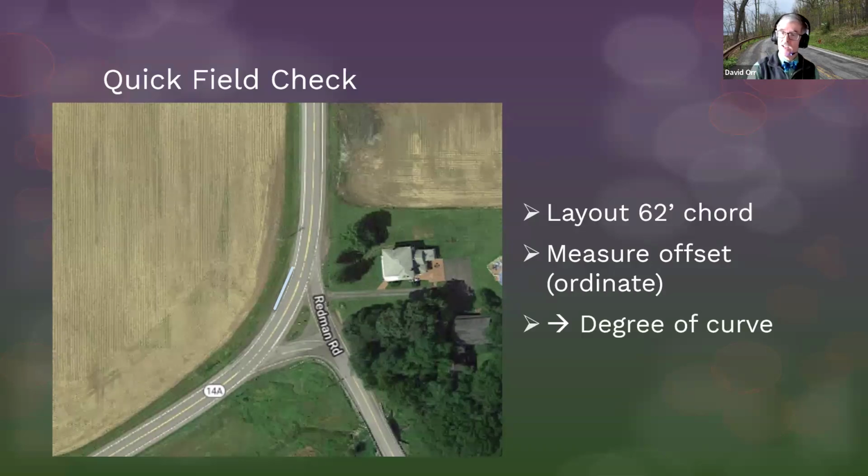And that distance is what's known as the degree of curve. And we all learned that in highway engineering, and we all completely forgot about it. That's where it comes from. It comes from old railroad engineering stuff, and allowed them to figure out how much offset they'd have, how they would do their rails in a particular situation, because rails, of course, were still straight, or they had to bend them a little bit. So how do you do this?